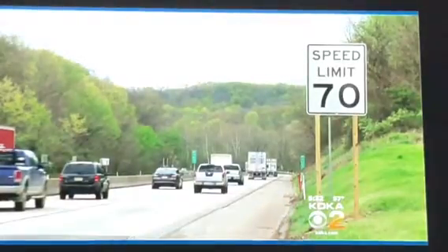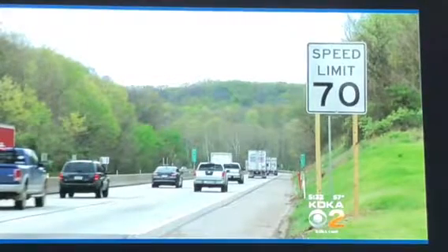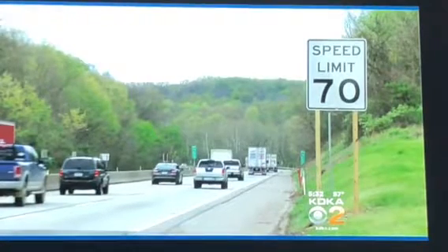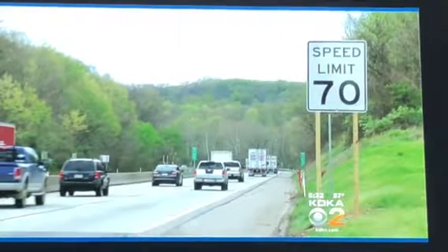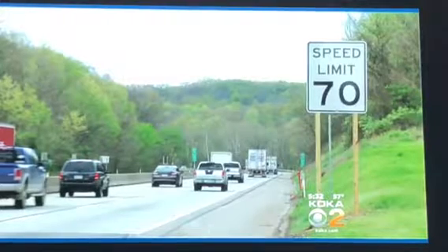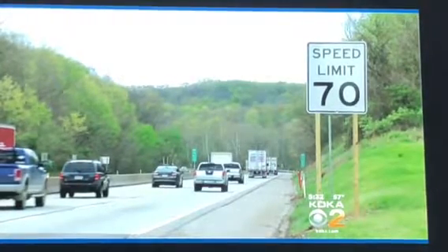Our team decided on 3 goals for this control system. First, the car must reach a terminal velocity of 70 miles per hour, the speed limit on most highways. Second, the car must do so in about 4 seconds to ensure the car isn't merging too slowly. And lastly, the system must limit the overshoot to 10%, so that the max velocity of the car is kept to 77 miles per hour to avoid being ticketed.